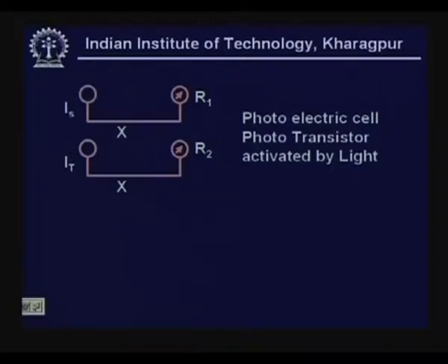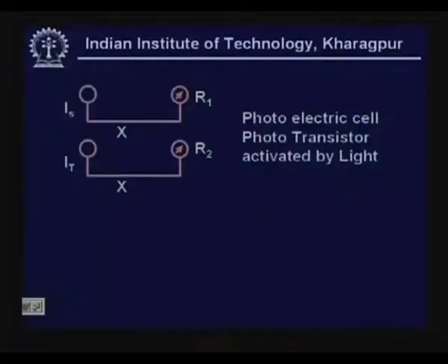Instead of varying the distance, if I use a lux meter and position it at a certain distance x on the photometric bench from, say, a standard lamp and get a reading R1, and again on the same bench I replace the standard lamp by the test lamp and maintain the same distance x between the lamp and the meter, I get a new reading R2.